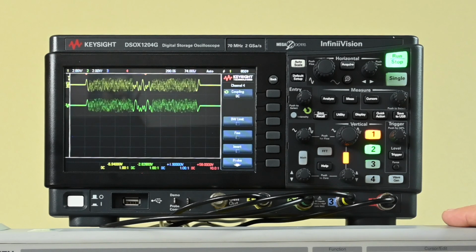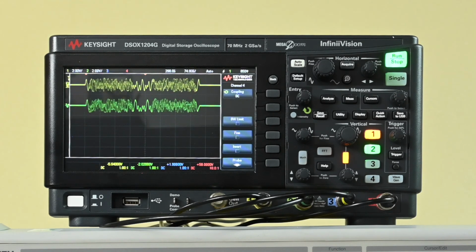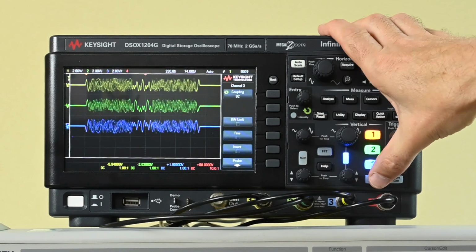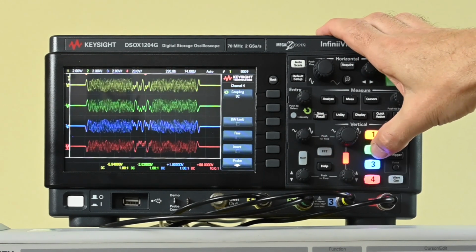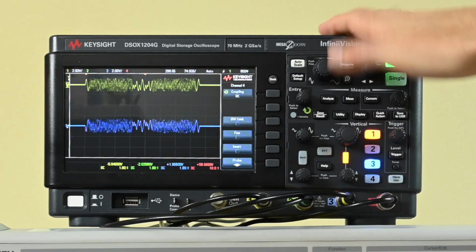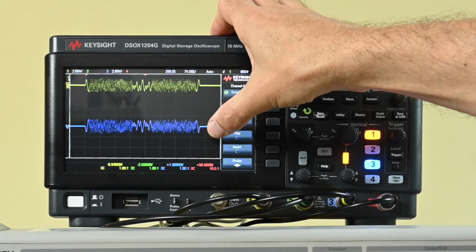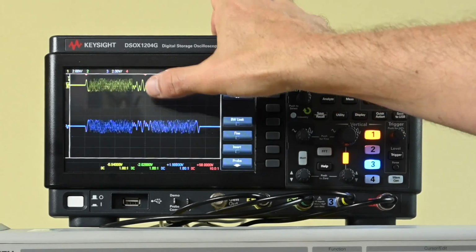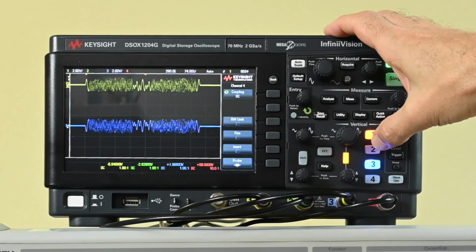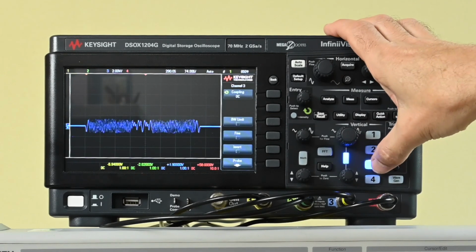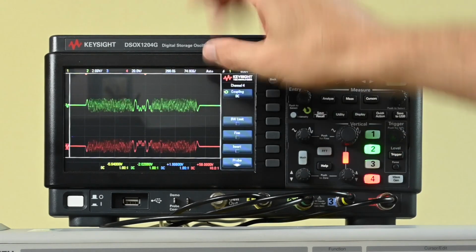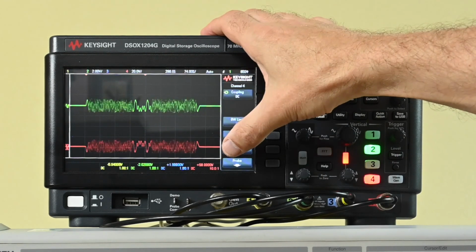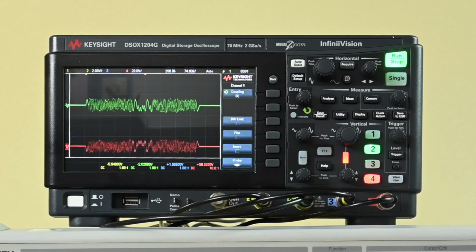One of the nice things is also that the Anritsu as a standard also has differential outputs. With a lot of other devices, that is actually an expensive additional option. And so I also connected the 2 differential signals to the scope. So what I'm just going to do is disable 1 and 3. So we see the I and the not I, the inverse I. And we see the inverse I is exactly the opposite of the I, and in the same vein, if I activate channel 2 and 4, we see the Q signal and the not Q signal, where the not Q signal, if you look well, is exactly the opposite of the Q signal.